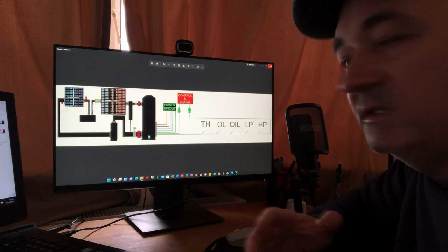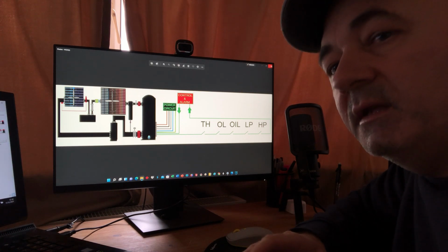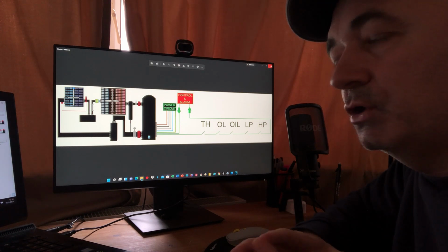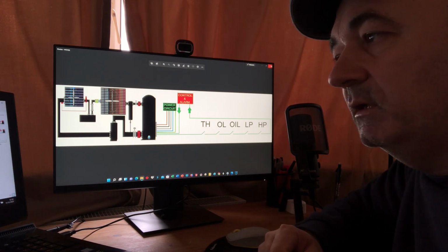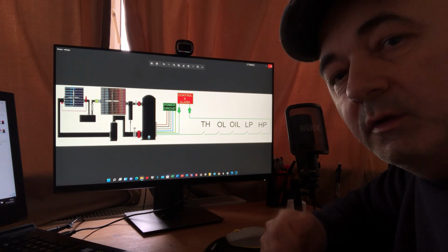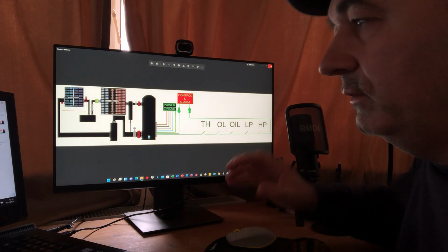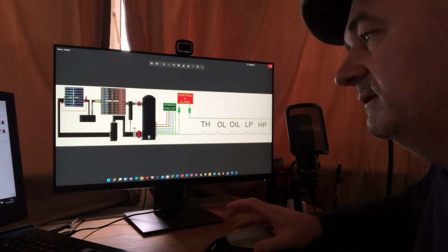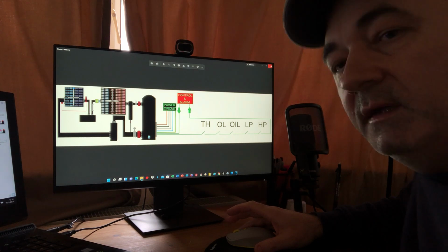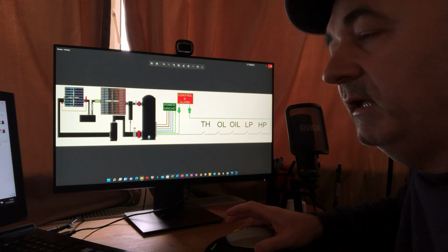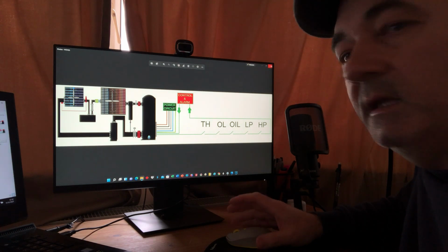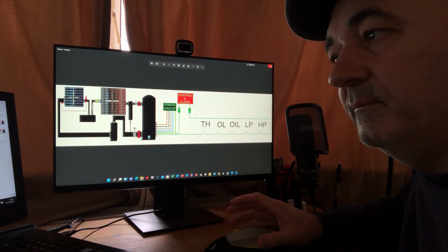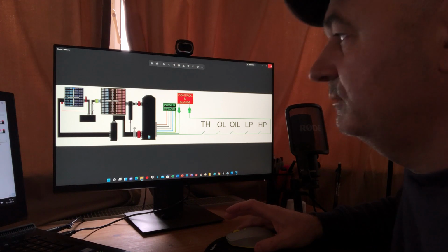If the client wants to spend more money, he can use either building management control or a programmable logic controller. I have other videos. If you look, they can be individually wired into the programmable logic controller inputs, and then you can have each fault individually, and that's a little bit convenient for the customer and for the technician, because any fault can be identified much faster, and then the customer can save a lot of money.